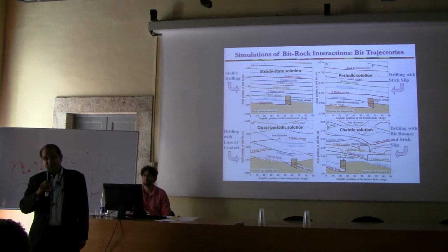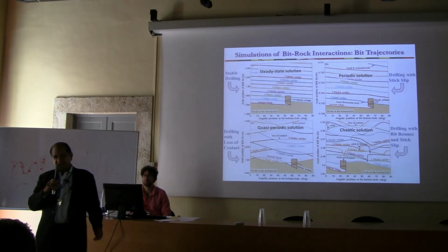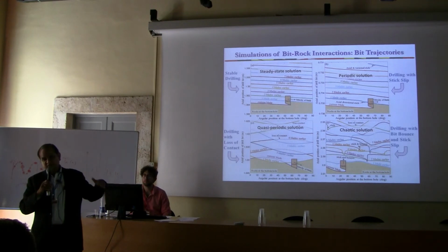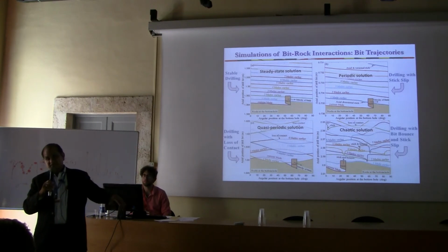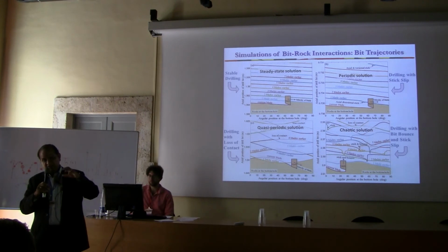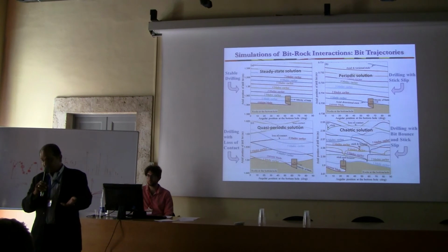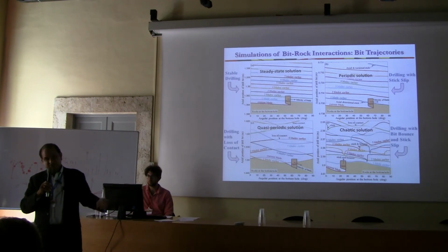One is deep drilling. Deep drilling would basically mean, if you're drilling in the ocean, how deep could you go to hit the oil beds way below? That's one area where the buoyancy effects become very important. The second is when you're drilling for oil, a certain reserve may run out of oil, so you may have to go a little bit at an angle. Horizontal drilling. For that, the drill string will be curved.